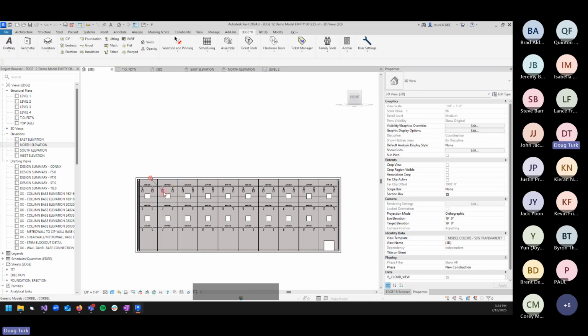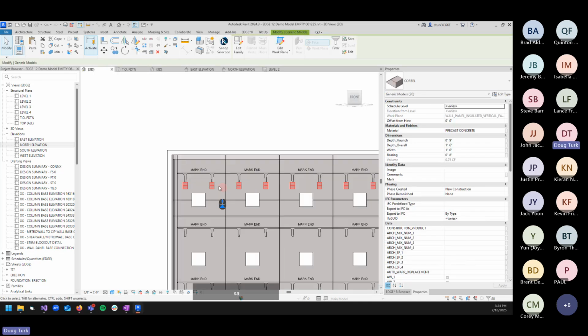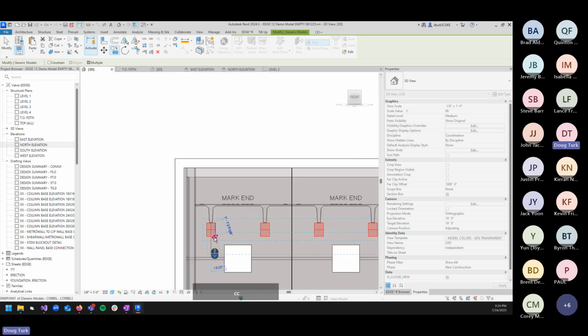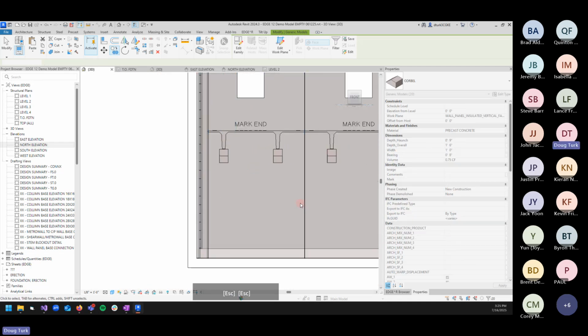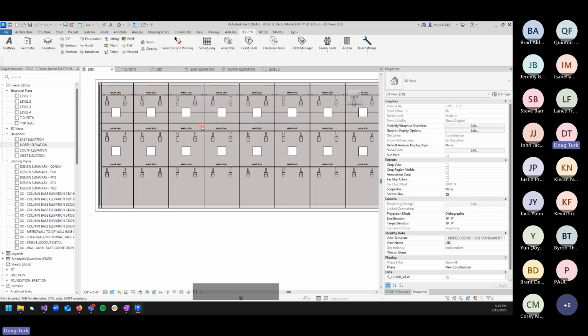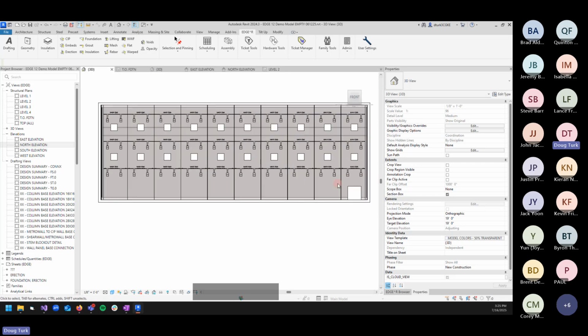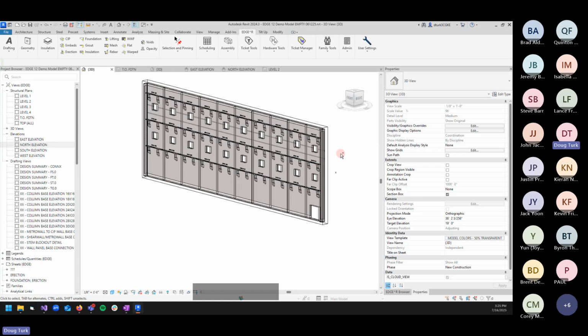And then we can just go ahead and copy these down using this point on the stems as a reference. And now those should all be nice and lined up for our span of walls. Again, we're only doing this for one span of walls, but you could very easily copy these things around to the other spans. In the interest of time, we're just focusing on these. So we've got our corbels on this side.